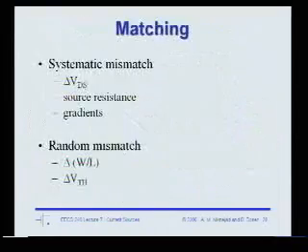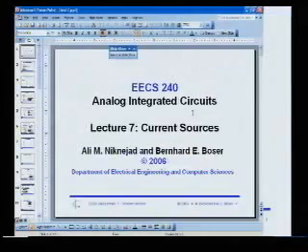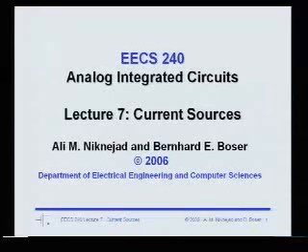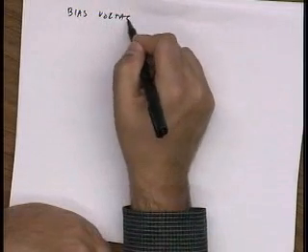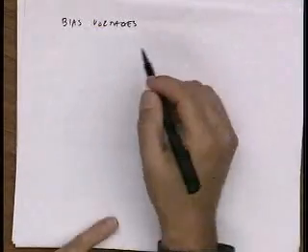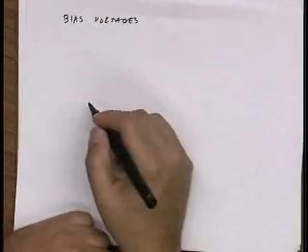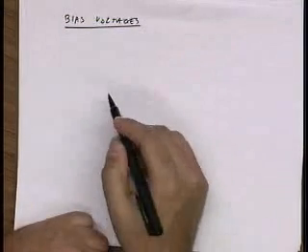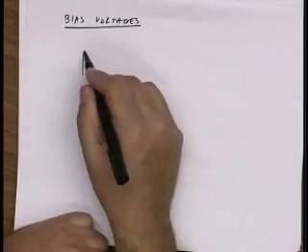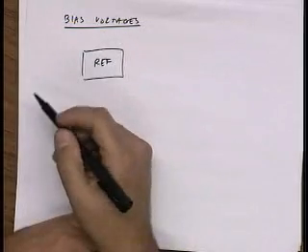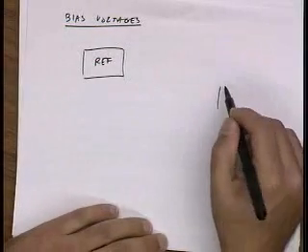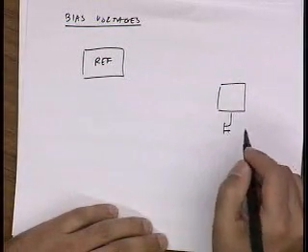So, in fact, let's maybe skip ahead and talk about, it's not even in this lecture. Okay, so let's talk about voltage. Let's talk about this general idea of basically routing bias voltages. Okay, and one way to look at it is I could have one cell that generates some reference voltages for me, and then in order to generate bias currents for different blocks, I could just have current mirrors.